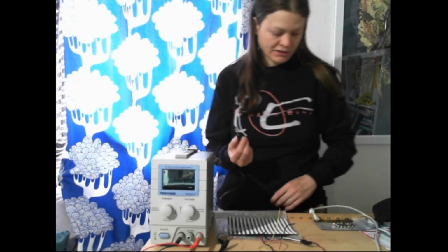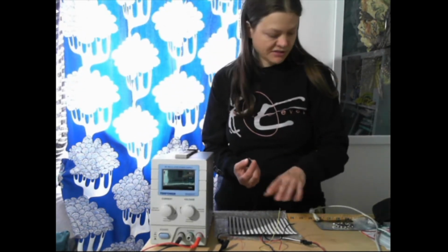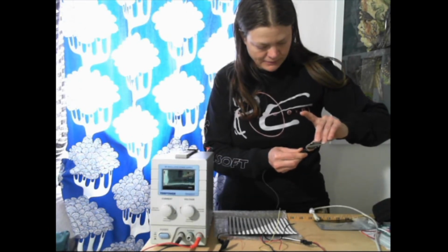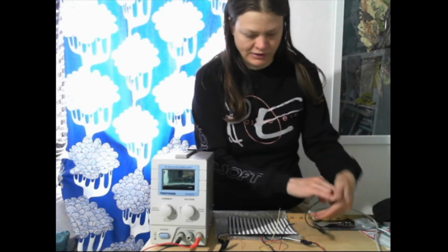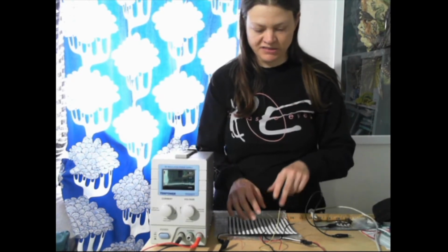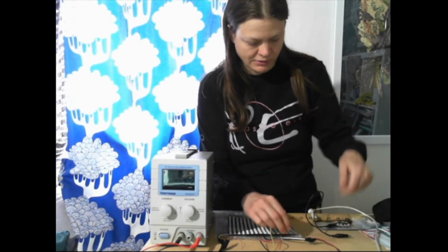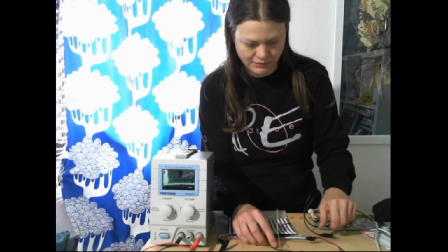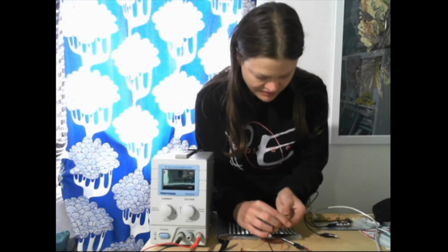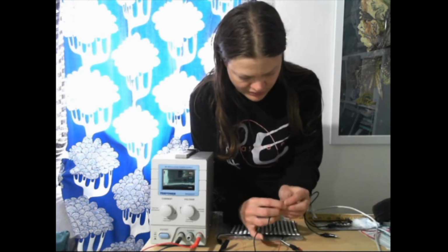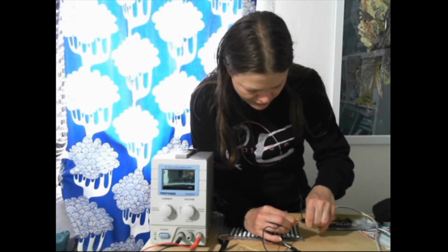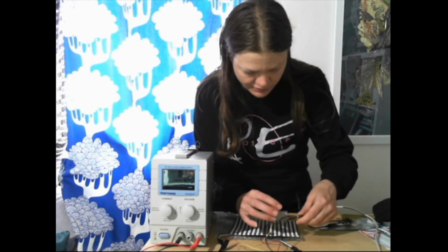We need to connect all the grounds here, so we're going to connect it to ground on the Circuit Playground. There we go. And we're going to connect it to both of the grounds on the matrix. So this one in the middle, and this one on the first part, the data in for the matrix. And I kind of like to just hold them together like this, and put this guy on here, make sure it hits them both pretty good.